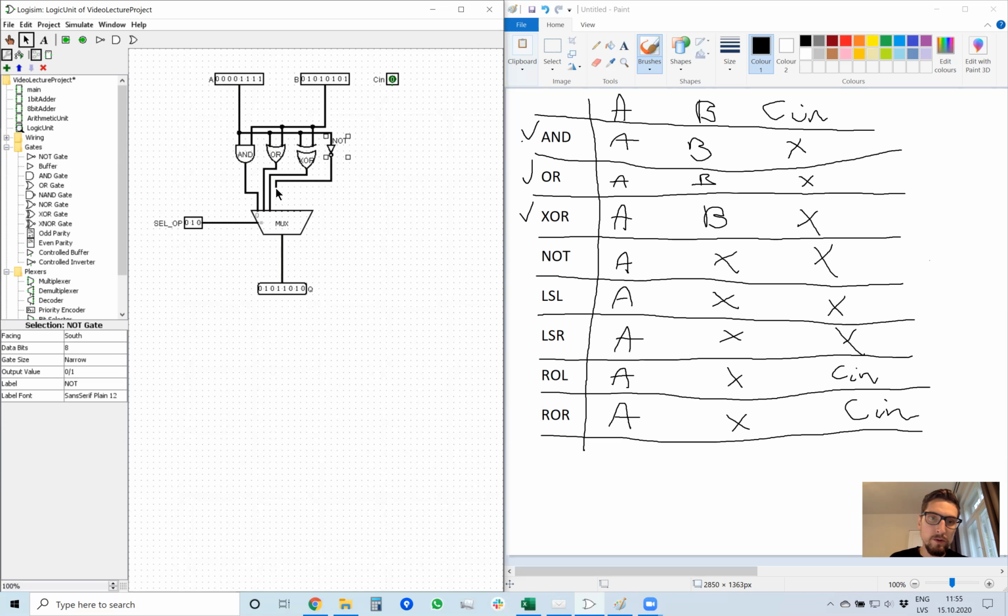And we feed it to the fourth input, counting from 0 it's the third, of this multiplexer. And now, if I select operation number 3, counting from 0, then it just inverts all A bits. This multiplexer is selected to forward that input, and here is Q. Q is the opposite of A.